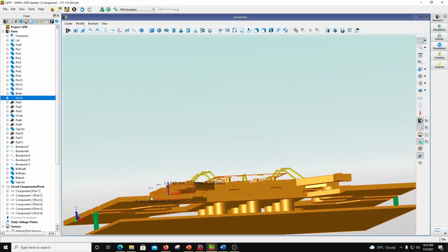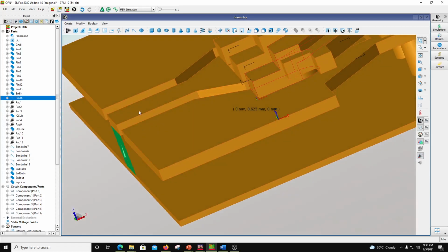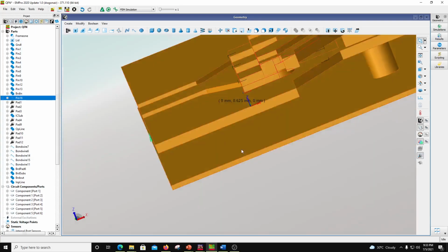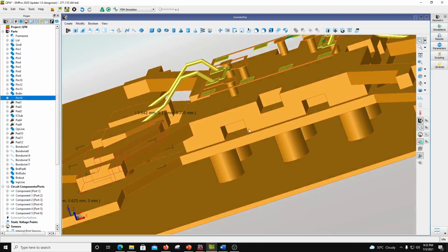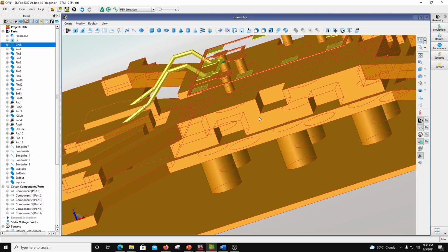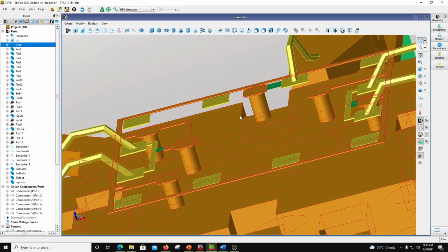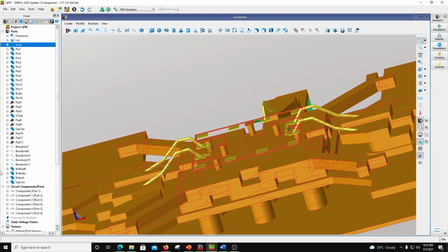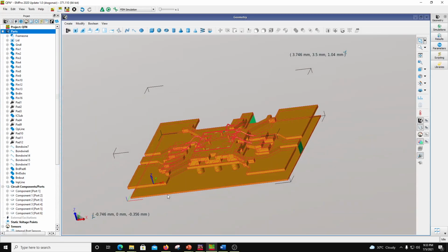The ground comes for the terminal, the ground comes from here, and this is a transmission line, and this is a board, right? So this is the ground, and for a chip the ground comes from the via onto the lower pedestal of the QFN, and then it goes up through substrate via onto as a coplanar structure over here. You can have ground routing on here, right? So I guess you understand this is what EM simulation is all about. Okay, so this is a 3D simulation in EM Pro of a QFN package.